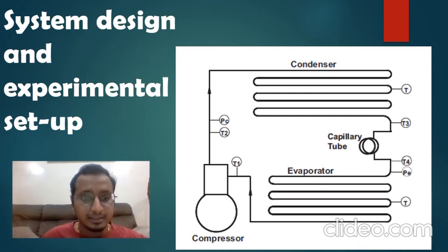Insulating tape was wrapped around the probe to make sure of good contact and also to prevent any convection effect of ambient air on the temperature reading. It was required to measure the water consumption rate due to evaporation in order to compensate the water. The water consumption rate was measured by using the variation of water level in the tank during the test period. Having the water level variation and the area of the water tank, the volume consumed could be calculated.